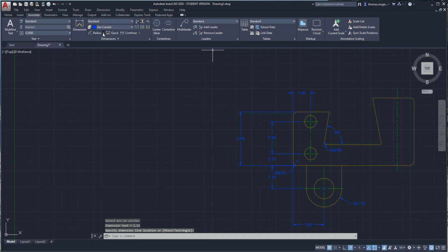And then I've got diameters also. And again, the diameter is the complete circle value. And so I'll put a diameter dimension here, or I can even move that out here. And I can also put a diameter dimension here. And again, diameter dimensions, again selecting those circles. Back to linear, we can then do overall dimensions from the endpoint to an endpoint.